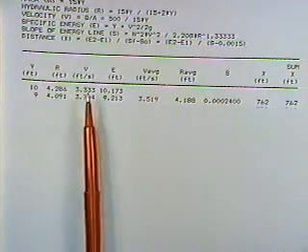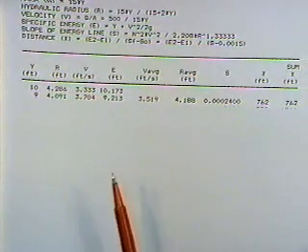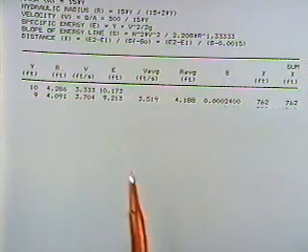We need the hydraulic depth, the velocity. The hydraulic depth is just the area divided by the wetted perimeter. And so we know that the area is the discharge rate divided by the velocity. The area is just 15 times y. The width is 15 feet, so 15 times y is the area.